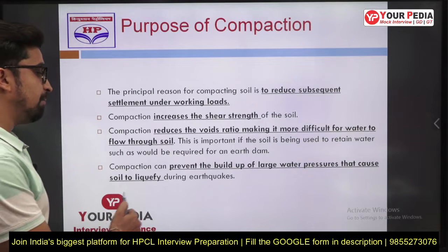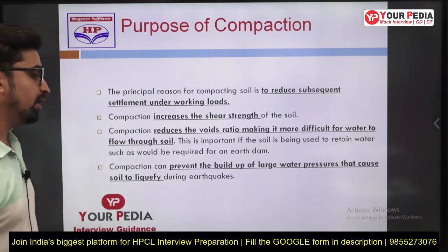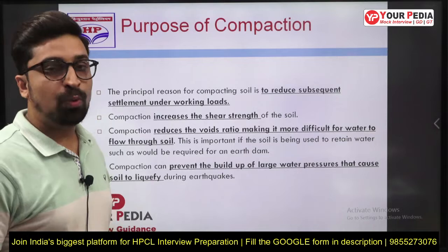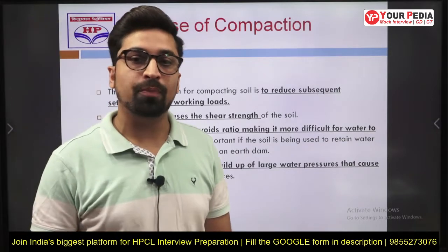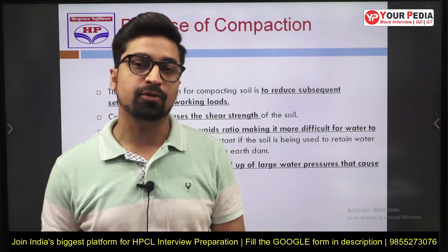Also, compaction can prevent the buildup of large water pressures that cause soil to liquefy during earthquakes. When the void ratio is less, the pore water pressure will be less and hence there will be less chance of liquefaction during earthquakes.